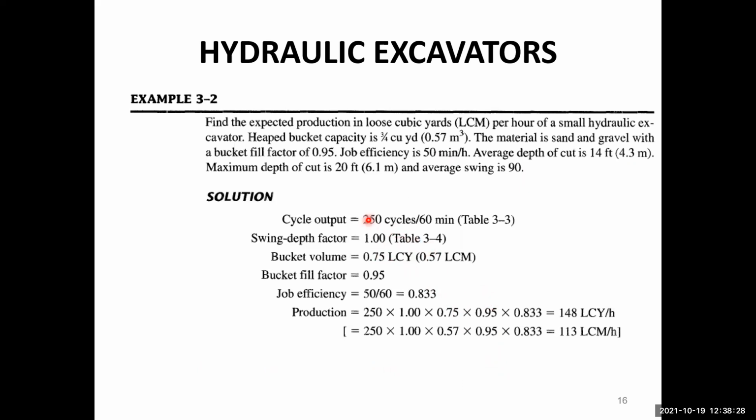So C is 250, S is 1. The bucket volume is 0.57 cubic meter, which is given. Bucket fill factor is 0.95. Job efficiency is 50 divided by 60, that is 0.833.